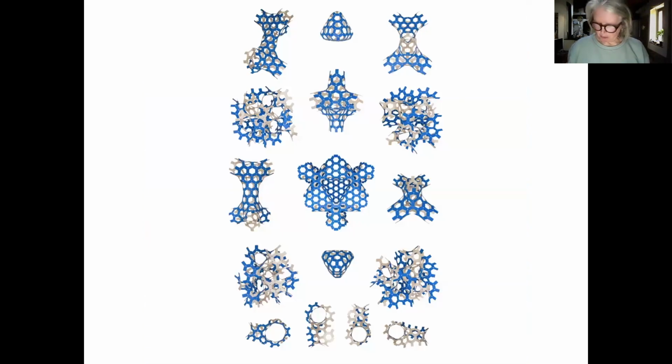As I say, I've worked with bamboo because that's what I have. And recently, we've also done some workshops where bamboo has not been available. So then we've looked at the possibilities of varying this material and transforming it using, in this case, plywood pieces. Here again, they're colored on one side to give a definition of the surface, but these are basically a thin plywood rectangle connected with reciprocal node connection. Each of the vertices connects 3 pieces of wood, and we looked at the variations of the different combinations within that fairly constrained vocabulary of elements.